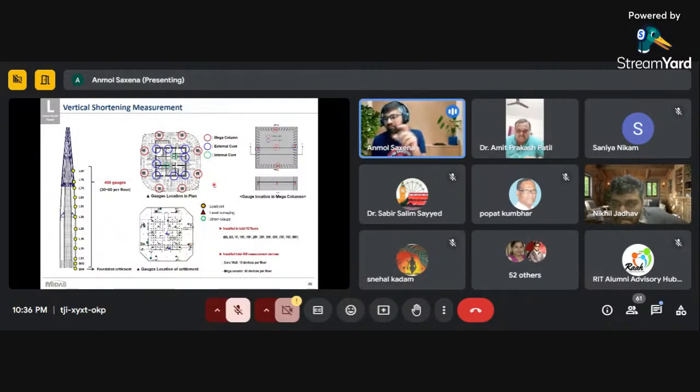How do we deal with these values? Basically, we again have to update the model which we prepared for the pre-analysis, in such a way that it shortened by exactly 25 mm in the software itself. Then again we will apply the corrections in the site for the above stories.